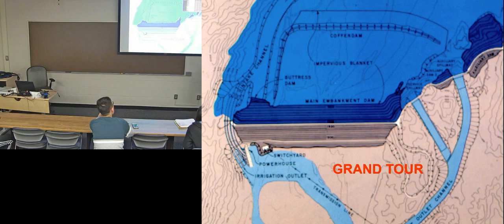to supply the irrigation water, there are tunnels over here on the right bank. It's called right bank because you look downstream. That's the right-hand side. 4 tunnels, well, they are key to my story today. We'll talk about those quite a bit. There is the impervious blanket upstream. Why do we have an impervious blanket? What does that do for us hydraulically? We'll talk about that. The spillways.